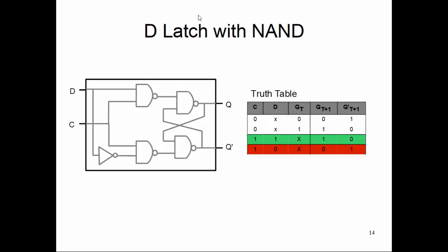All right, so that's the reason why we want to go to a more complicated storage element, which makes sure at the iteration t plus 1, GT plus 1 is not going to corrupt my GT at that iteration. GT plus 1 will only appear at the other side of the storage when my iteration is going to be GT plus 2. So it's kind of pushing it to the future. We want to make sure this partial calculation only appears in the future iteration. So that's the reason we are going to go with the D flip-flop.